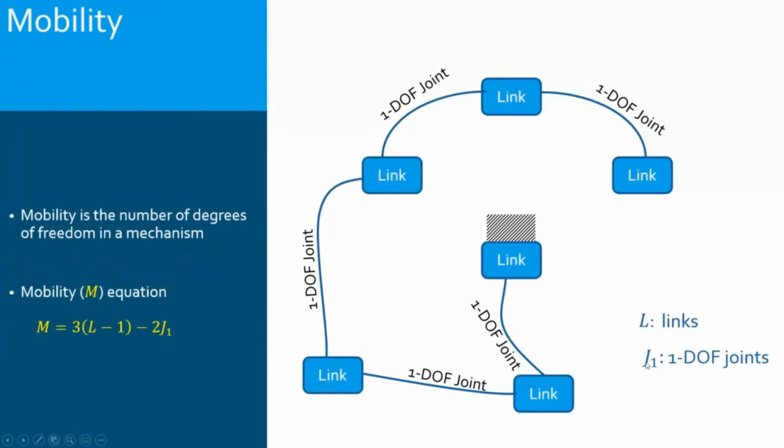If I have the general J1 number of lower kinematic pairs, I am treating lower kinematic pairs and 1 degree of freedom joints as the same because in planar motion they are the same. The 1 degree of freedom joints or lower pairs are the pin joints and prismatic joints, and the high pairs or the 2 degree of freedom joints are the cam and gear joints.